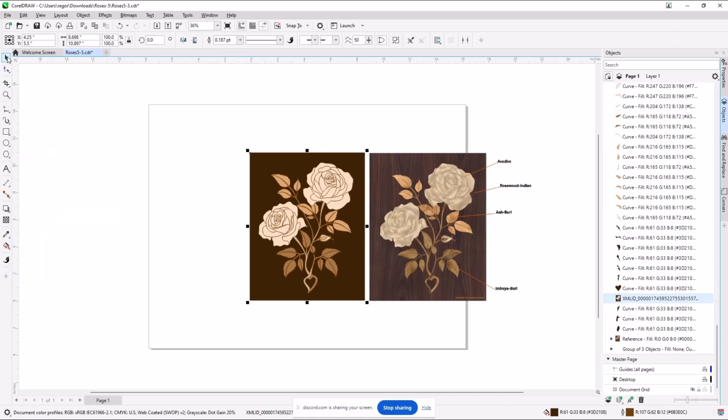If I look at it carefully, I've got a pick tool, which is how you select objects. I also, if you look at the tiny corner triangle here, if I left click on that, all of a sudden I have a context menu of freehand pick, free transform, or pick. I leave it on pick. The next one down is the shape tool, which is accessible by hitting F10 if you're somewhere else on the screen. But this one also has different choices, things like that.